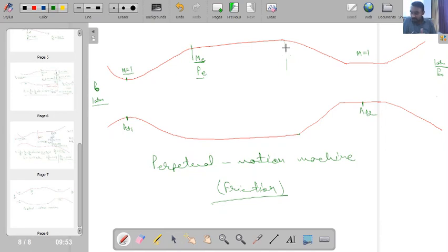So what ultimately I will be finding is some oblique wave will start and go like this, another will start at this point and go like this, then these will interact over here, slightly refract, and this will lead to a chain of shock waves. Obviously if we are having the chain of shock waves, these will make the flow non-isentropic, and then we will be having a decrease in stagnation pressure.